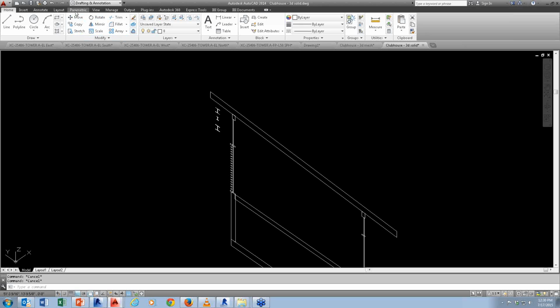Because it's also pretty cool because it's also parametric. When you add a section line, it will generate that information, and then as you move that section, it will regenerate that object again. But it has to be 3D solid, okay? So if you have people working on Revit, and then the person wants to do, let's say, a detail in AutoCAD, this is a good opportunity so they can actually study a bunch of sections, okay?